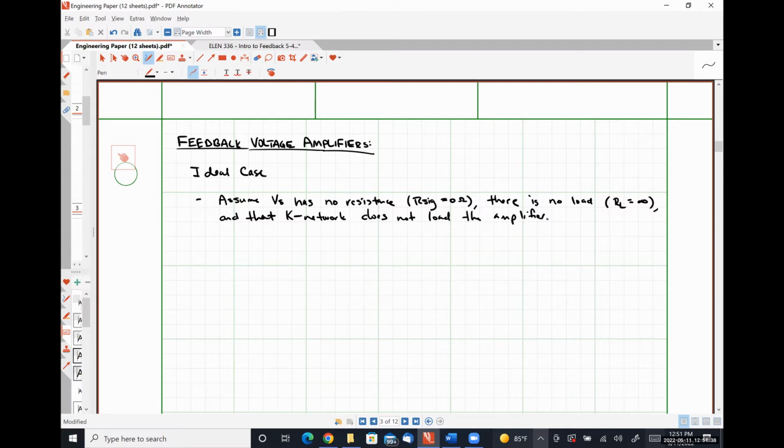Okay. My topmost circuit, I'm going to call my open loop gain circuit, or my A circuit. And because we have a voltage amplifier configuration here, we're just going to use the practical voltage amplifier model like we developed back in circuits 2. So by that, I mean specifically, I'm going to have something that looks like this. My voltage amplifier is characterized by some input resistance, Ri.